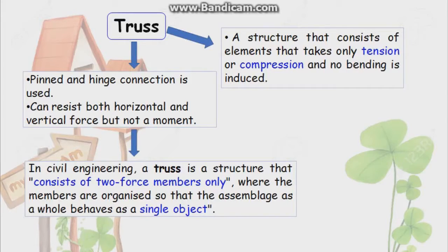Now I will present on truss structure. A truss is a structure that consists of elements that take only tension or compression. Pin and hinge connections are usually used in truss structures. It can resist both horizontal and vertical force but not a moment.